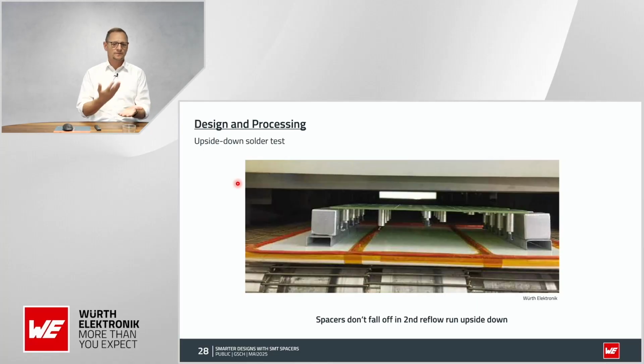Of course, all the components here, all the spacers have been soldered regularly on top, yeah? And then we flipped the PCB to see what happens if the solder melts again, if they just fall off. And I can assure you nothing fell off. We even made it harder, and we put screws and washers to the spacers, and they even didn't fall off, and now they're qualified for a 5-time reflow test.